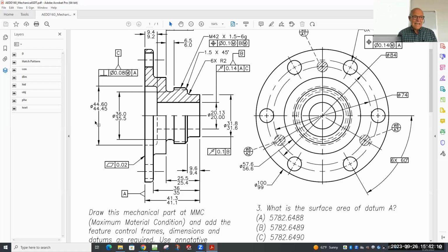So in some fields, the actual tolerances aren't ever specified because the understanding is they're big enough, so you're going to get them. Carpenters never see a print that says, when you cut this, plus or minus a 16th of an inch. Carpenters just build it as close as they can. And when they build it as close as they can, it's easy to do and it works because the tolerance itself is big enough for variation so it doesn't affect the function. Does that make sense? So far, so good?